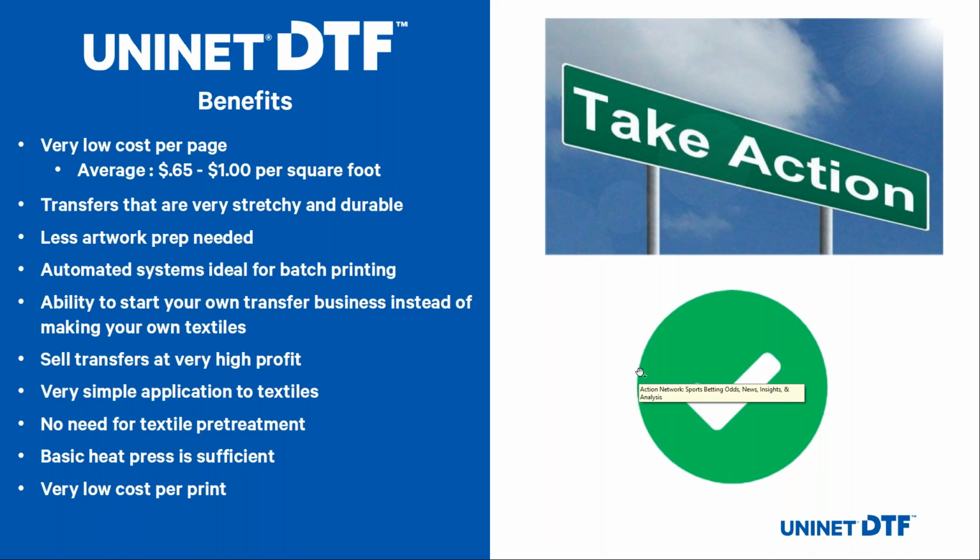Very simple application. Once you have a cured transfer sheet, you're basically pressing for 15 seconds at 310 and you're peeling warm. You can just let it sit for about a minute and peel. Then you just hit it with a post press and you're done. You don't need a crazy heat press for this. You could use a clamshell or cheap press because you're really not so concerned with pressure, and temperature can vary a little bit as well.